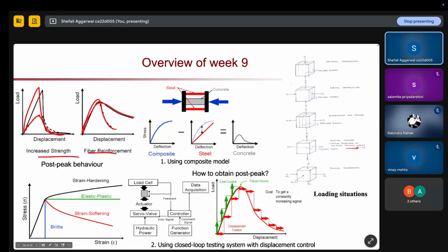Another one is biaxial tension. In that case both are in tension, and your concrete will fail in a sudden way. It will have a full crack and come apart in two pieces. And last and important is triaxial compression, in which we apply loading in all three directions.